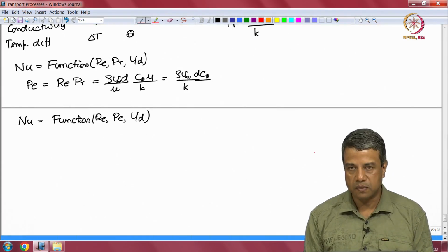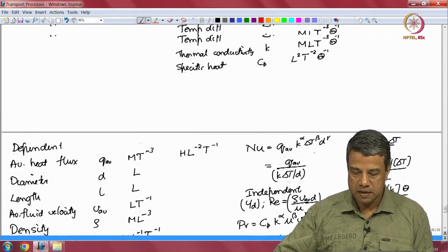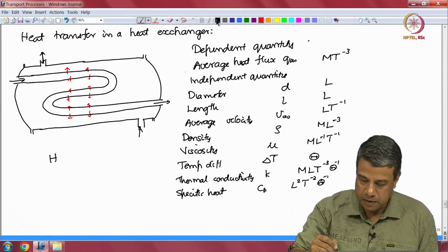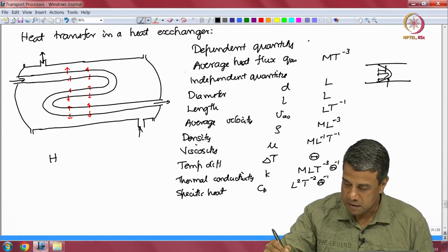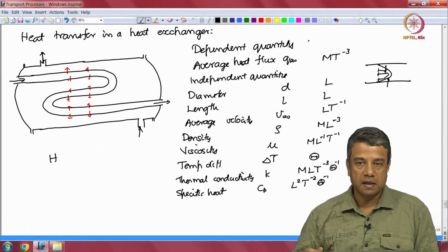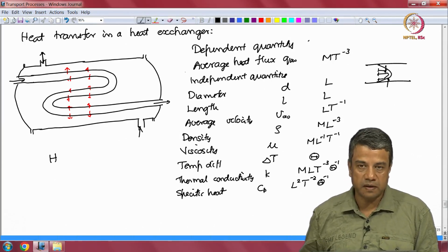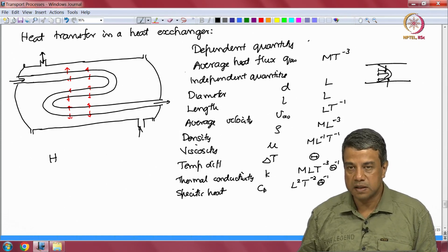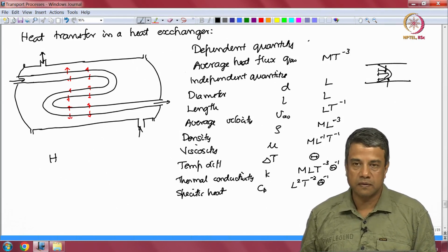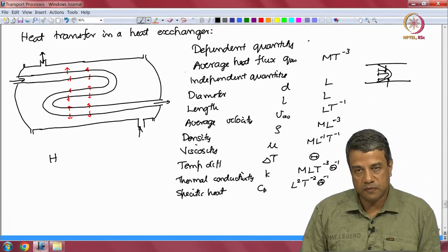Now, in the limit of low Peclet number, you would assume that diffusion is dominant. However, that regime is not actually of interest for a heat exchanger. For a flow in a pipe, if diffusion is the dominant mechanism across the cross section, convection is not important. That means that the temperature will equalize across the entire cross section of the pipe before the fluid has moved very far. In that case, there is not much use in having a long pipe, because the temperature is equilibrated before the fluid has moved very far.